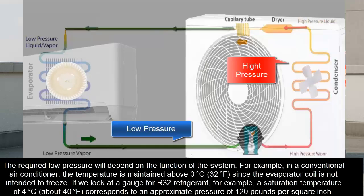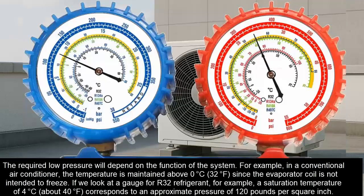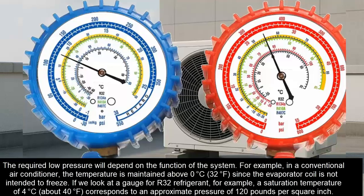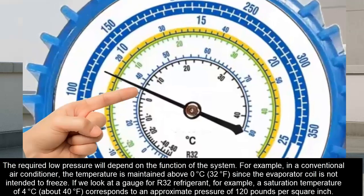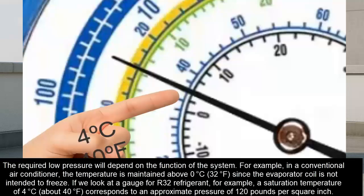The required low pressure will depend on the function of the system. For example, in a conventional air conditioner, the temperature is maintained above 0 degrees Celsius, 32 degrees Fahrenheit, since the evaporator coil is not intended to freeze. If we look at a gauge for R32 refrigerant, for example, a saturation temperature of 4 degrees Celsius, about 40 degrees Fahrenheit, corresponds to an approximate pressure of 120 pounds per square inch.